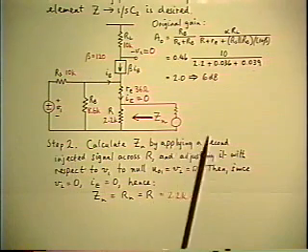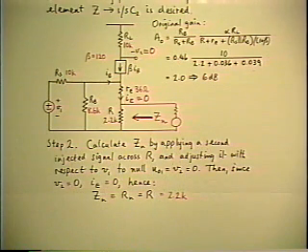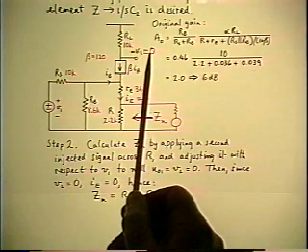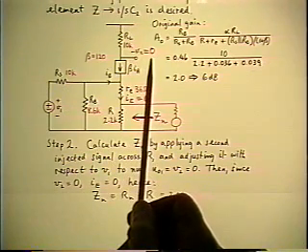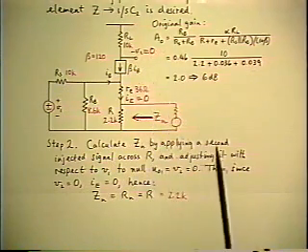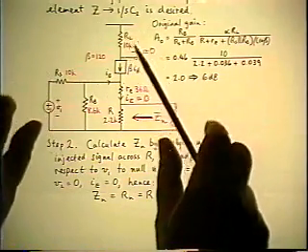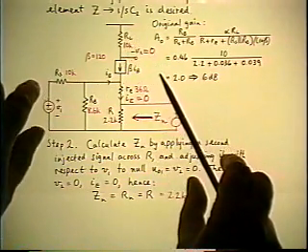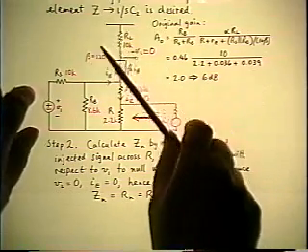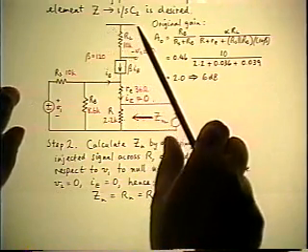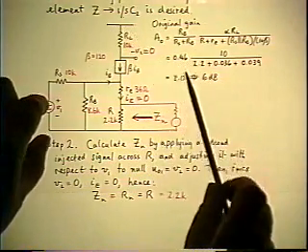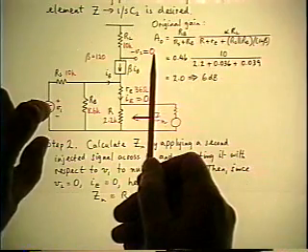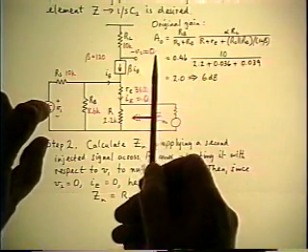But we have to adjust those two sources to achieve a specific condition. Namely, output number 1 is nulled. Output number 1 is V2. So you visualize twiddling the knobs, actually using one directly from the generator and the other one going through the shoebox with magnitude and phase knobs. And you twiddle the magnitude and phase knobs of the second input relative to the first one until the meter hung on V2 goes to 0. Then you don't twiddle anymore.